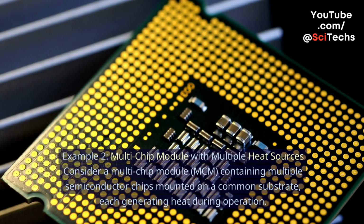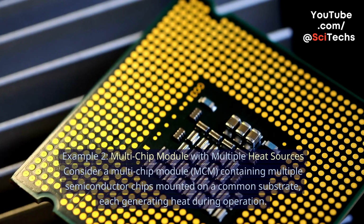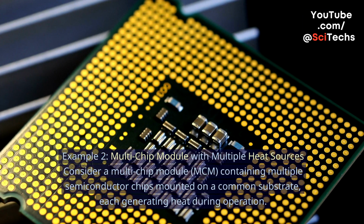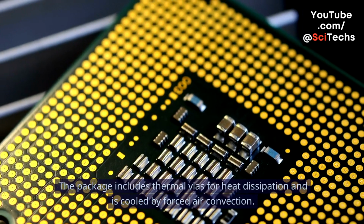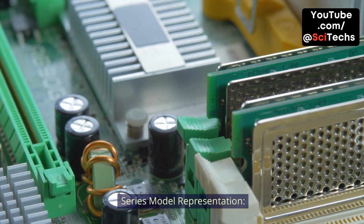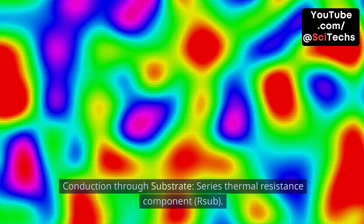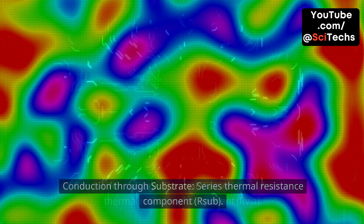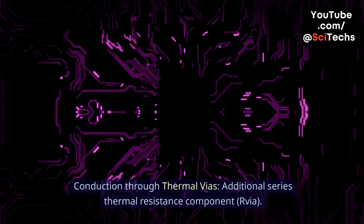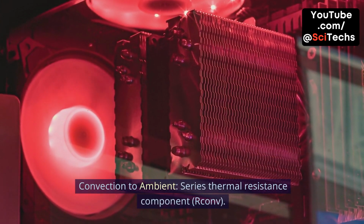Example 2. Multi-chip module with multiple heat sources. Consider a multi-chip module, MCM, containing multiple semiconductor chips mounted on a common substrate, each generating heat during operation. The package includes thermal vias for heat dissipation and is cooled by forced air convection. Series model representation. Conduction through substrate, series thermal resistance component, R sub. Conduction through thermal vias, additional series thermal resistance component, R via. Convection to ambient, series thermal resistance component, R conv.